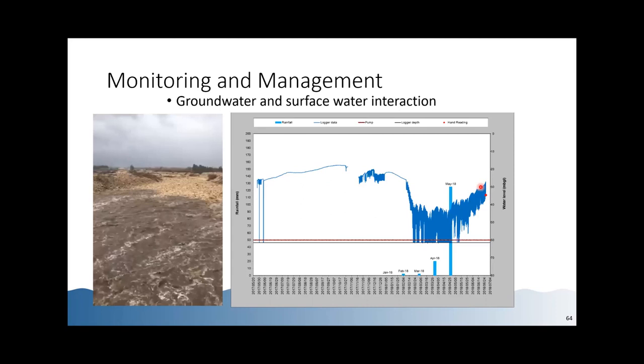And this is a fractured rock aquifer. So yeah, we're sitting at fractures about 40 meters, but obviously also relatively quickly recharged, especially by the alluvial channel. And this is the sort of data that you need as a borehole operator if you're using groundwater, to be able to know when you can start using your borehole at capacity again, and how to incrementally phase that back in.